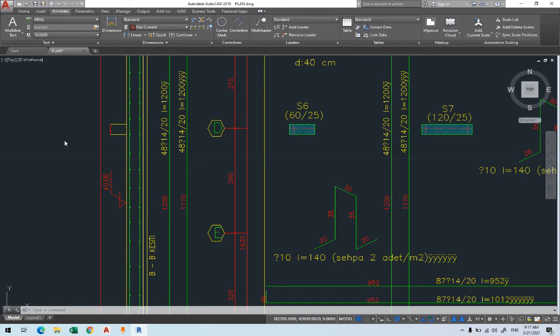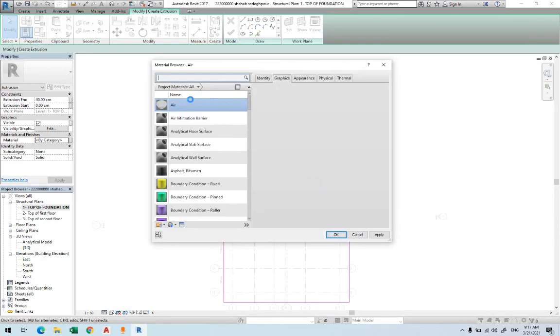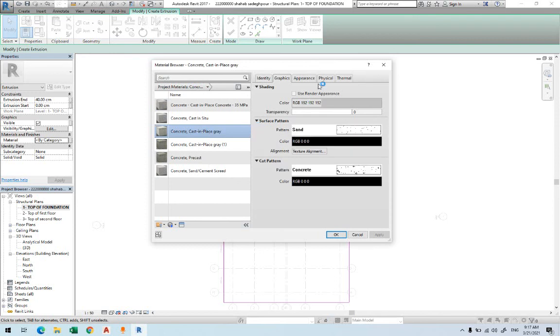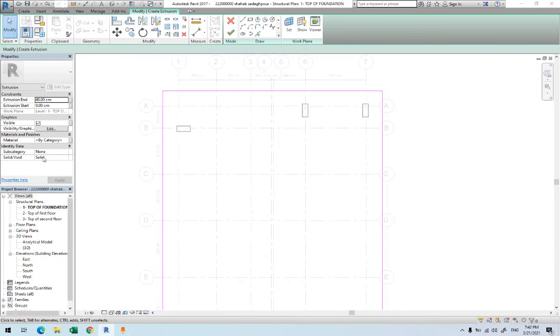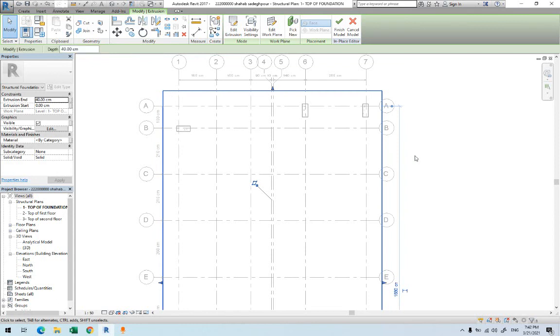Those will be a part of the design that will be provided to the engineers, because they say, okay, we have the foundation, it's this concrete with the strength that we have. So I can go to here, concrete, for example this one, and we can add the properties if you want to. Now let's say that you forgot to select the material. You have the extrusion and the foundation in the right place, and on top of the foundation we can press this right button and it will create the foundation for us.